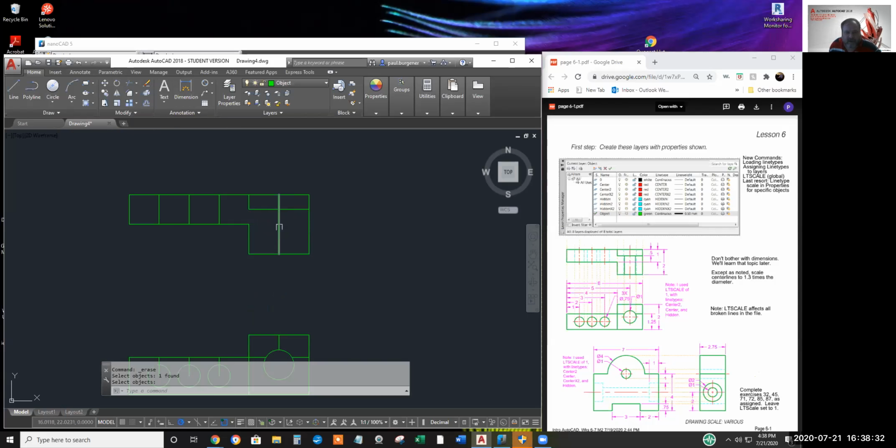Okay, I'll offset this line, which will eventually become a red center line, I believe on the center layer, not center 2. Where's offset? Offset, half of 1 is 0.5, so I'll offset it each direction 0.5. Okay, trim what will eventually become hidden lines.